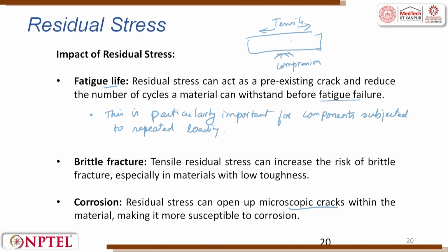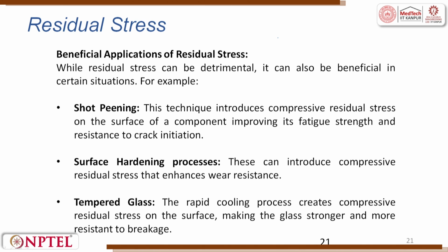When you do that, there are cracks. Through these cracks the corrosion grows. That is why the residual stress can open up micro cracks within the material, making it more susceptible to corrosion. There are some benefits also because of this residual stress.